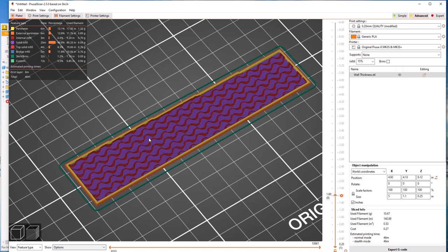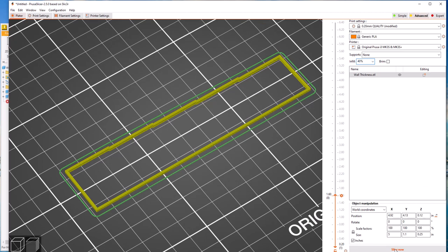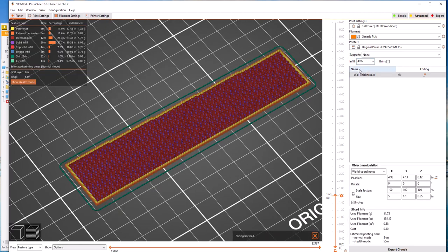So we're now at the inside layers, and it's doing this pattern here at a 15% infill. If I change that to, let's say, a 40%, I don't think I've ever printed 100% anything. In the end, this part is going to be super strong for what you're doing, interconnecting all these different weave patterns, but that's a 40% infill.